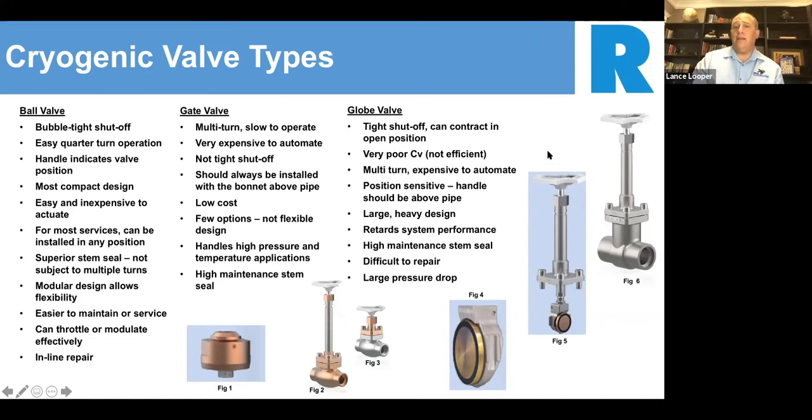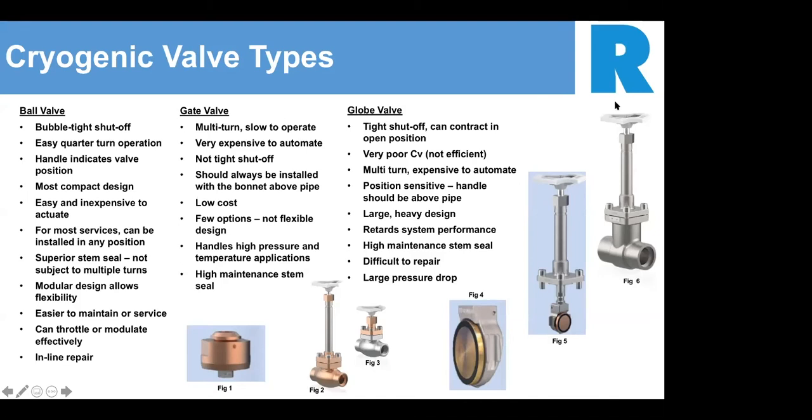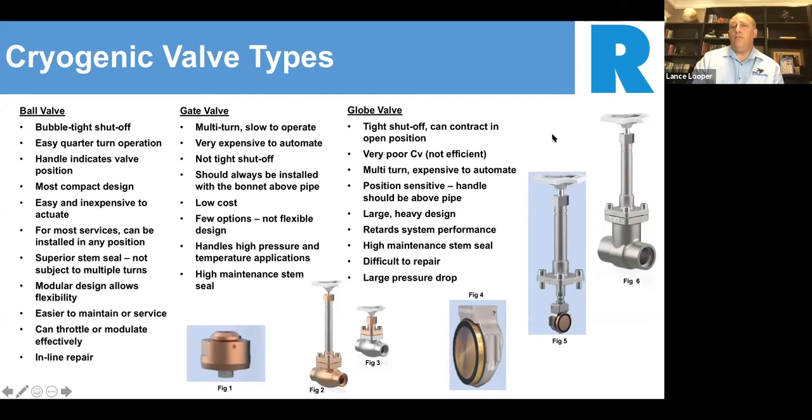They're easy to maintain, very easy to service. You can pull a ball valve out of the line and replace the seats in them. So in general, a ball valve can be used for a lot of different applications. If a person calls me and asks what I recommend, it's really application driven, to be honest with you. But a ball valve will give you a high CV factor, give you a lot of flow. And a lot of times, in most cases, especially for delivering product, it's a fantastic choice.